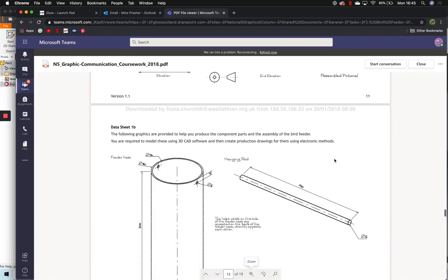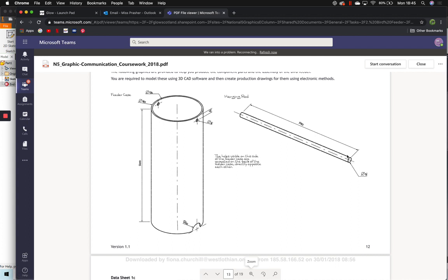So looking at our drawing, the hanging rod is circular in shape, and it's going all the way here. Now we're going to use the dimensions in this drawing to determine what shapes it's going to be. So because it is a circle and it doesn't change width the whole way through, we know that we are going to use the extrude command rather than revolve. So here it shows that the diameter of the circle is going to be 5.